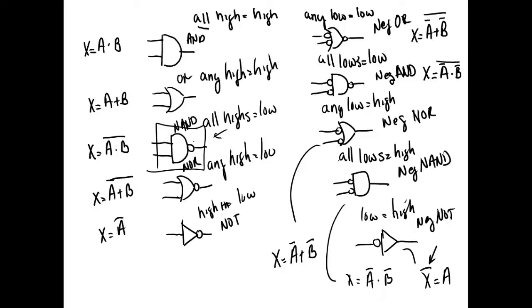A lot of times we'll look at some schematics, and you'll see they have a thing called spare gates. These were the gates that they just couldn't fit in. If you've got 6 gates inside an inverter chip and you only need 3, then you're going to have to use it. That's the only option you've got. That leaves you 3 that just go unused unless you can find a use for them. And we'll show y'all what you do.